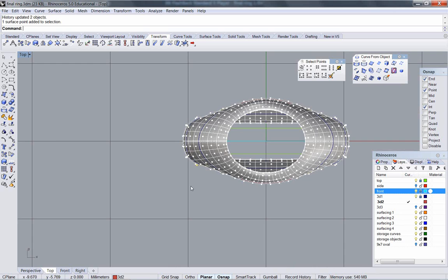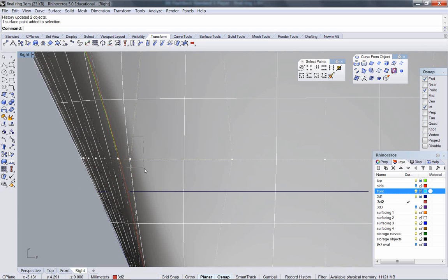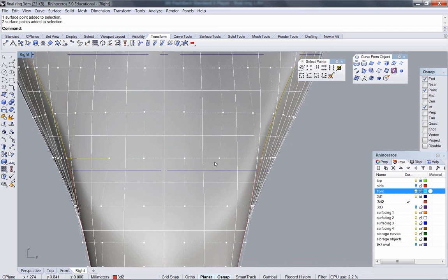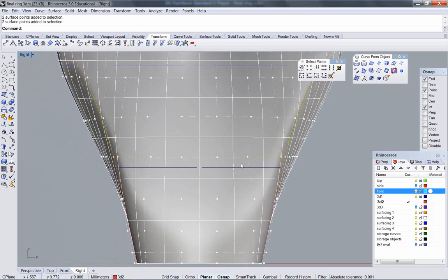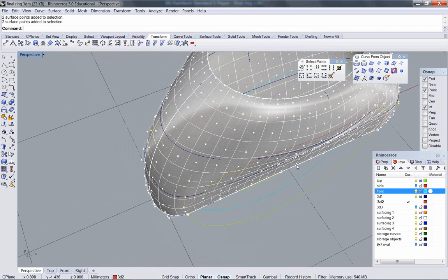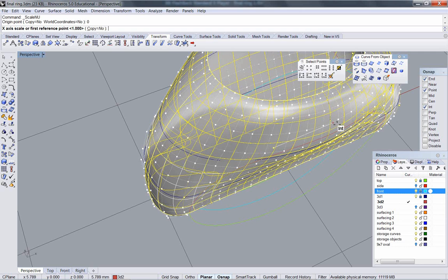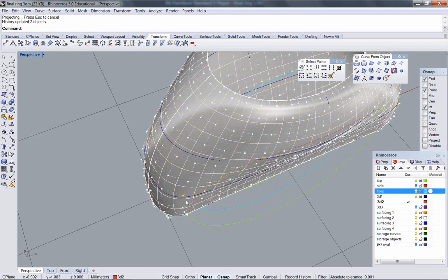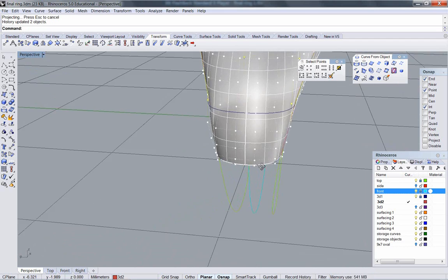I'm going to do the same here, which is dangerous because doing that here can create a knife edge in my casting. Just a little bit to relieve that bulge. Yeah, I like that.